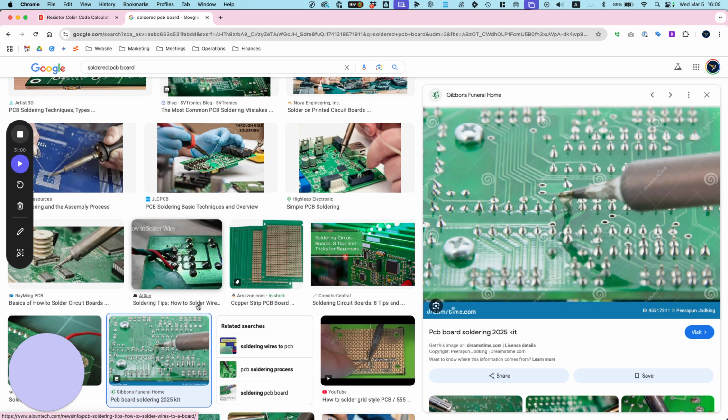What is the voltage we are dealing with here on this one? 9 volts. So before I plug it in, I'm going to first make sure my alligator leads are separated. I'm going to make it 0. Okay, it's on 0. This black one goes to this blue. This red one goes to the gray. Now I'm going to turn up the voltage to 9 volts. Oh, it's already shining. Look at that. Isn't it amazing? It works as intended.